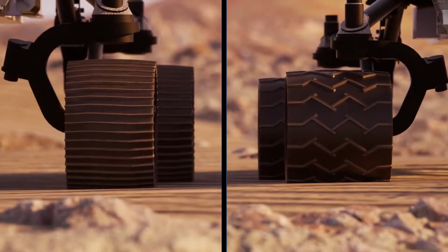The wheels of the Perseverance rover are slightly heavier, with a slightly thicker outer shell, and slightly bigger, so the outer diameter is larger and the curving radius is a bit less, so the stress is a bit less on rocks. It's slightly narrower, so the area on which it drives is less, so less wear there, and it also has twice as many threads, so it has higher friction in sand.